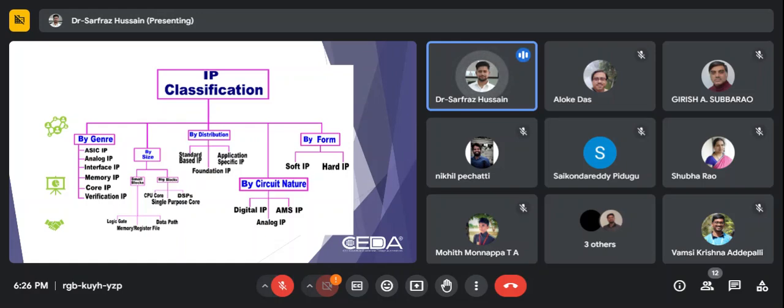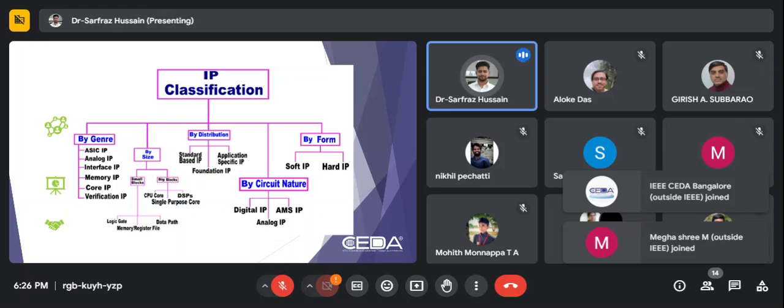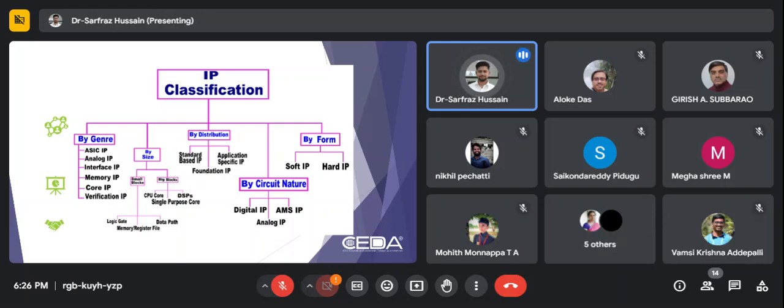Usually, whatever designs we see now are mostly soft IP. And if you want to create your own IP, let's say a particular standard cell, or a particular op-amp design all by yourself, then you can go for the hard IP. And by circuit nature, there is digital IP, AMS IP, and analog IP. Digital IP is different, analog IP is different, and AMS, that is mixed signal. If you go for mixed signal, those IPs are also different.